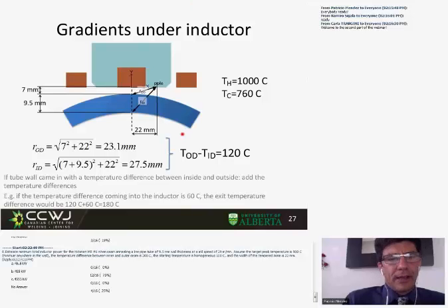So here we have an example calculation which we have seen in the online course. I don't want people to start doing very long calculations, so I spelled it out myself. This is the ROD, and we are using Pythagoras, like the triangle trig, to calculate this distance as the gap squared plus the half width of the pole squared. And the ID distance would be the gap plus the thickness, all squared, plus the half width of the pole squared. And with those two, we get these two distances.